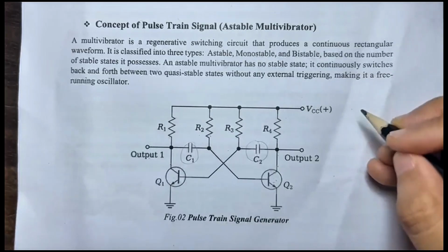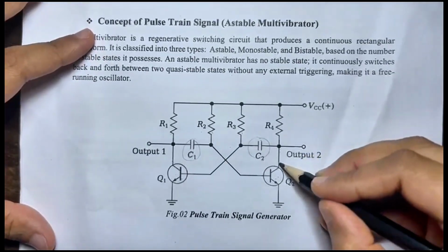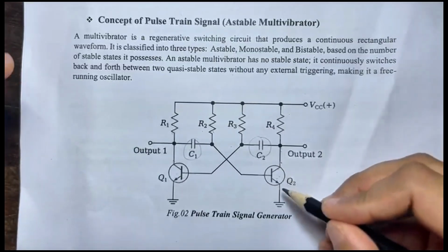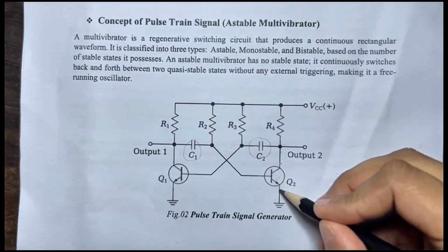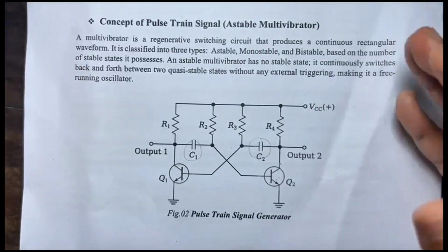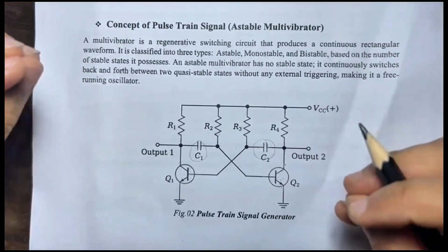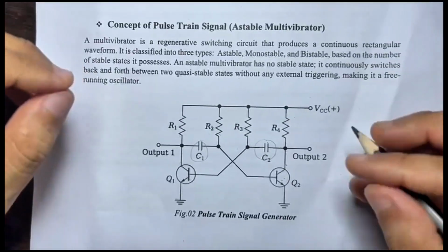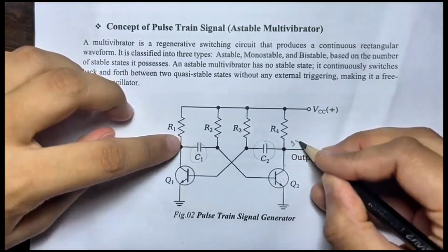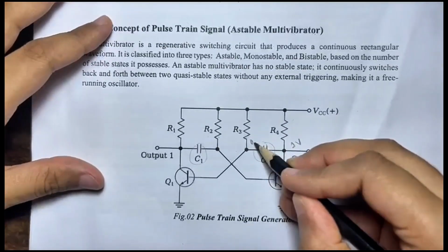As the transistors are in the saturation region, the voltage of the collector will be equal to the voltage of the emitter, that is 0, but the capacitor has to maintain its previous voltage difference between its two sides for some time. For this reason, the gradually increasing voltage of this terminal is 1 volt, and the voltage of the other terminal is 0.7 volt.